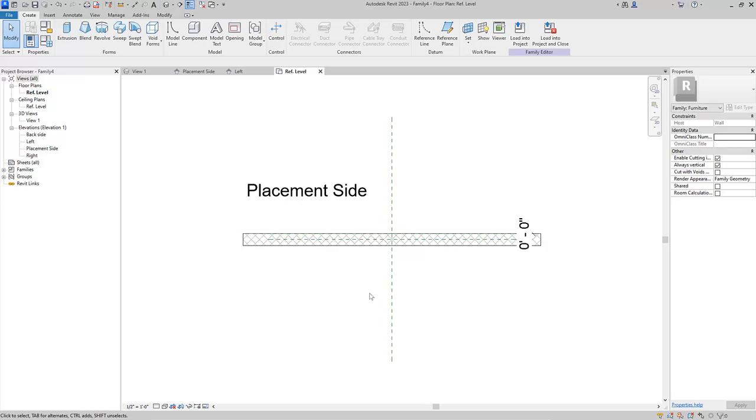As its name suggests, we can create the shared parameters once and then use these in multiple families. This, of course, is much more efficient. The other advantage is that shared parameters can be tagged and scheduled. We must carefully consider the management and naming of shared parameters so they do not conflict with other parameters within Revit. So let's see how we'd first create a shared parameter file.